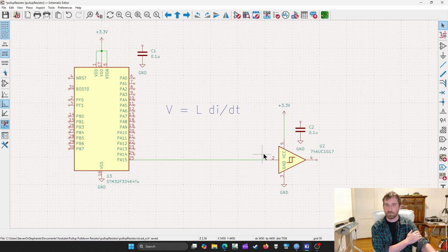So we think about, I'm going to switch my terminology to a decoupling capacitor, decoupling all the inductive nonsense going on here. So L di/dt. You saw in that 1980s board, they use traces, so L would be lower. So I want to talk about di/dt.